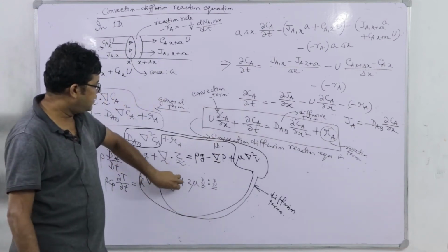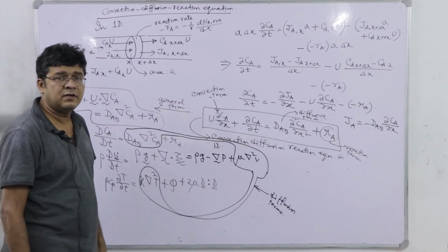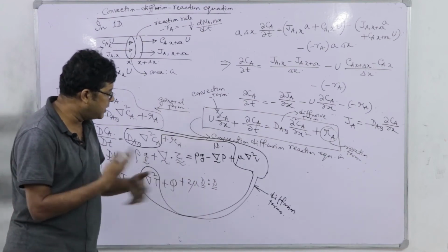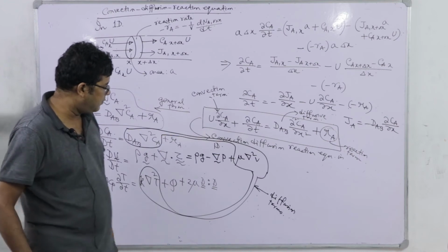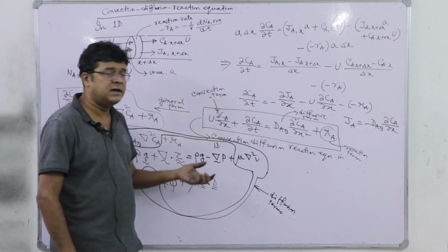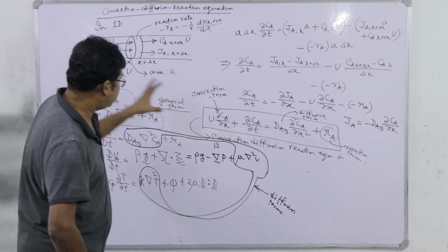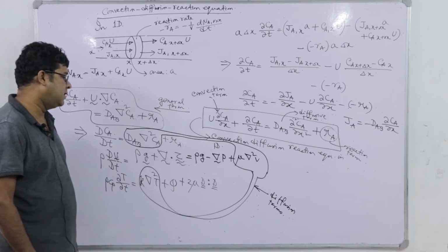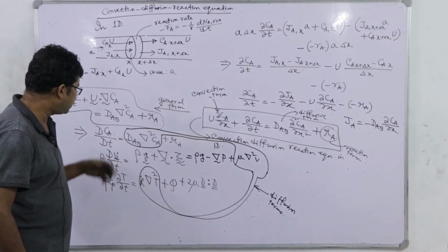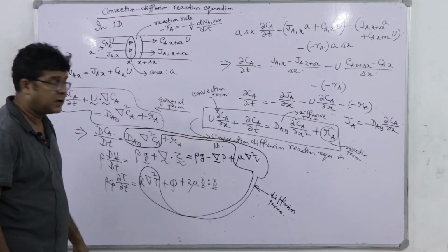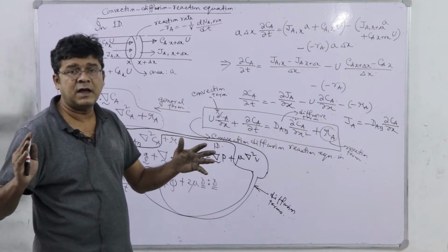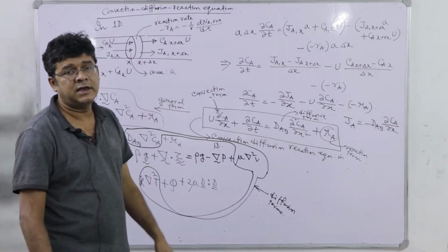Similarly, here Q is the heat generation or dissipation per unit volume of the system, and because of the fluid flow there will be frictional work which will finally convert into heat, which is the viscous dissipation term. So, they are either the generated term or the dissipated term. So, we have structurally three equivalent transport equations. One is transport of mass or mole, another is transport of momentum, another is transport of energy. And the convection diffusion reaction equation falls in the same category as the Navier-Stokes equation or the general energy equation in the case of heat transfer.